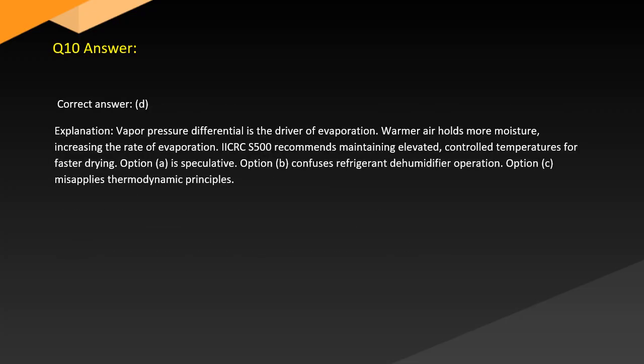Answer. Correct answer: D. Explanation: Vapor pressure differential is the driver of evaporation. Warmer air holds more moisture, increasing the rate of evaporation. HRConquer recommends maintaining elevated, controlled temperatures for faster drying. Option A is speculative. Option B confuses refrigerant dehumidifier operation. Option C misapplies thermodynamic principles.